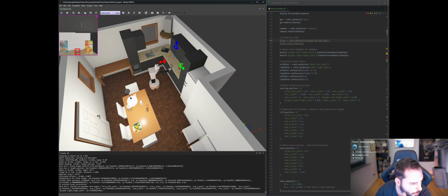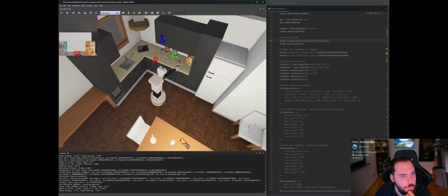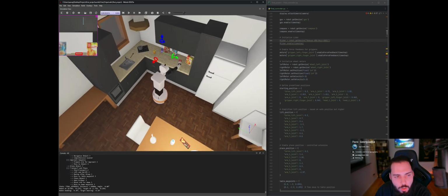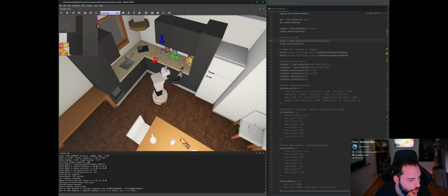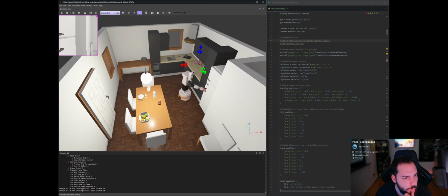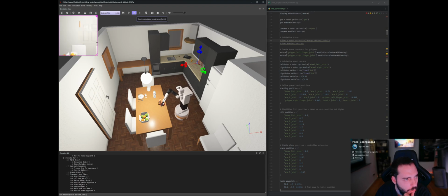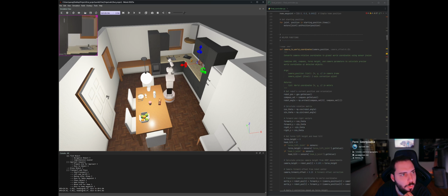Attempting IK for final target, and then IK solution found successfully. Started arm movement with angles, and then all of these angles were calculated from the inverse kinematics. And as you can see, it is pretty much spot on. We then have grasp, which you can see contact detected, grasp successful, lift sequence, and then object securely held. So the lift and verify worked. It'll then go on to move to the table. Drop it on the table, and then it should go back home.